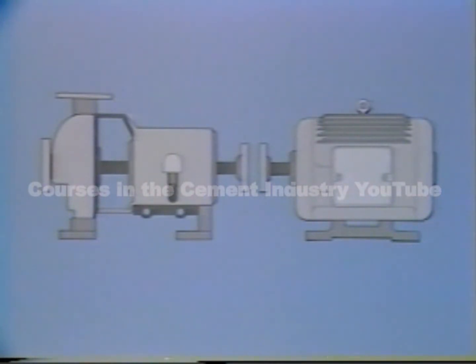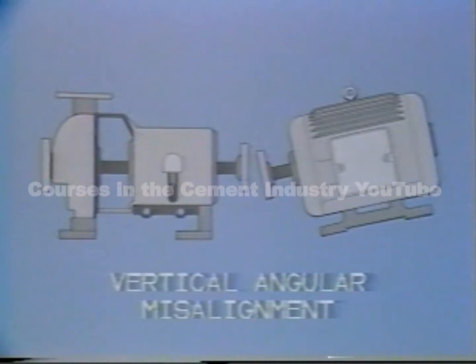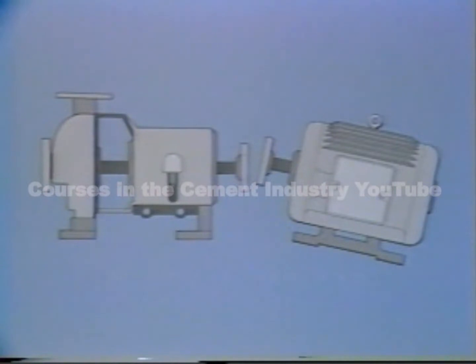If we introduce some angular misalignment, it's caused by raising or lowering one end of the motor. This creates the angle between the shafts. So this is called vertical angular misalignment. Anytime one shaft is tilted up or down in relation to the other shaft, vertical angular misalignment exists. Let's realign the shaft and look at the other alignment problem that can occur in the vertical plane.